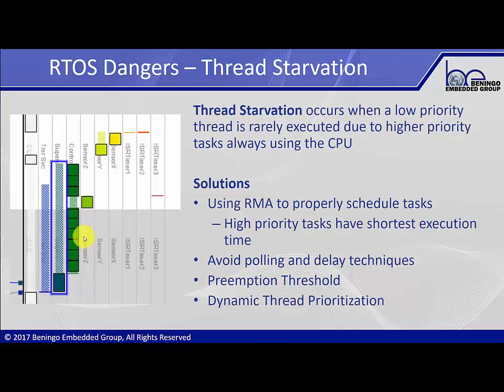So what you can do is instead select time slicing. And what will happen is that task 1 will start executing its code for the time slice. When the time slice is up, task 2 will then start executing its code. Then when the time slice is up again, it'll switch to whatever the next task is. They'll go round-robin style, but they get a little bit of CPU time in between so that they aren't completely starved of access to the CPU to run their code.